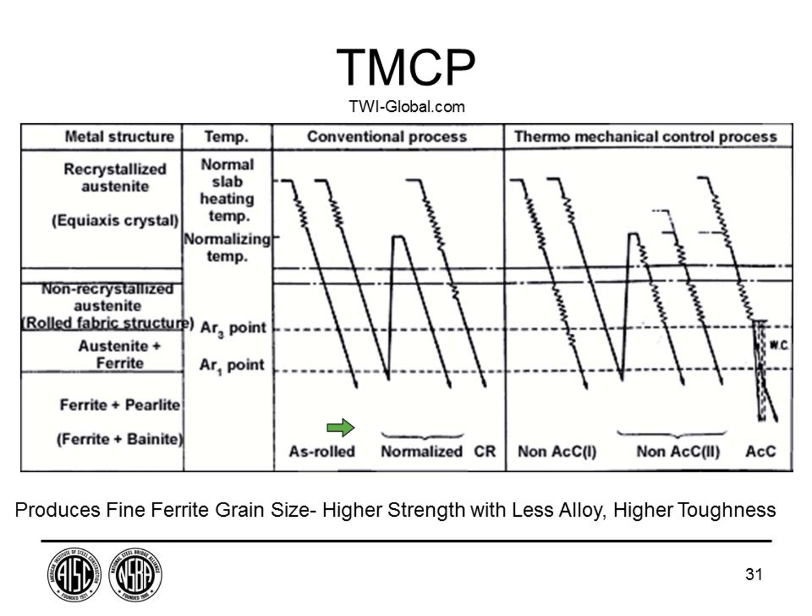You can modify that process. You can still do the rolling up at that temperature, cool it down, and then take it back up and normalize it. This is done to improve the properties of the plate and make them more uniform. Then there's an intermediate step where you do the rolling at a high temperature, but as it cools down into this range, you do some additional controlled rolling. This gives you a little bit more strength at this temperature.